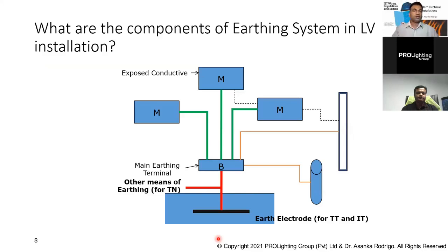And another thing is, when you look at this, the regulation discusses the different types of earthing arrangements and the earth connections as well. Because now you have to keep in mind, in the modern building, what they talk about is equipotential bonding. You have to have a common earthing arrangement, and the standard uses different terminologies, so sometimes people mix up. When selecting these earth wires, sometimes we call everything an earth wire, but it is not like that. There is correct terminology, and the selection of the conductors should also be based on that terminology.